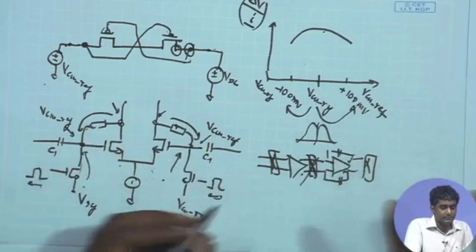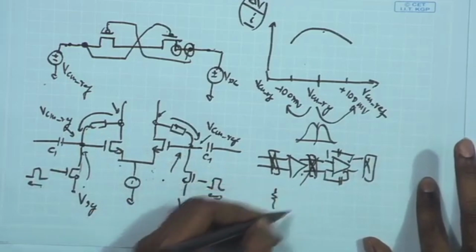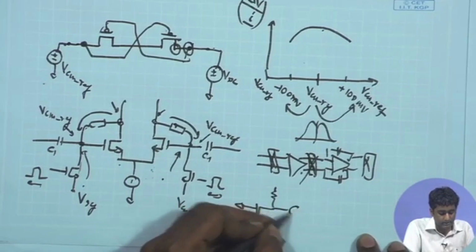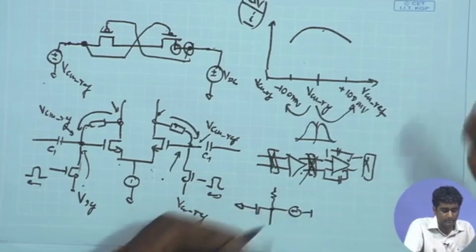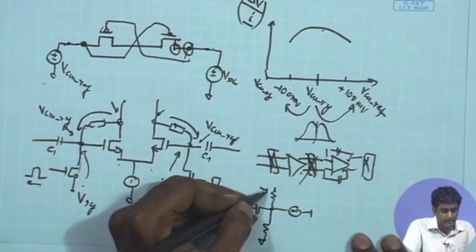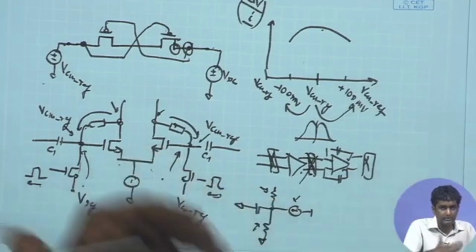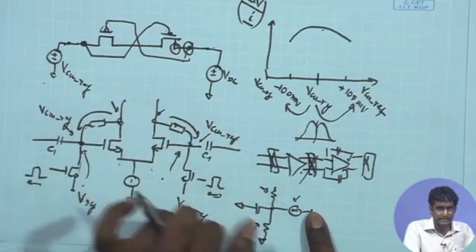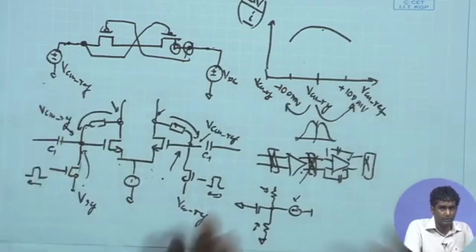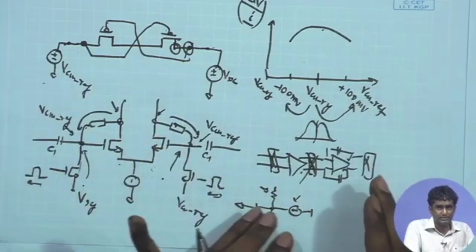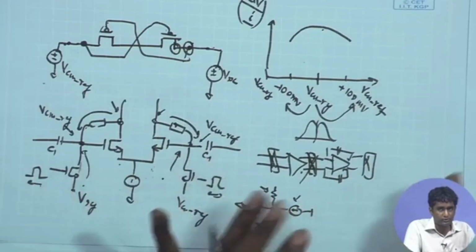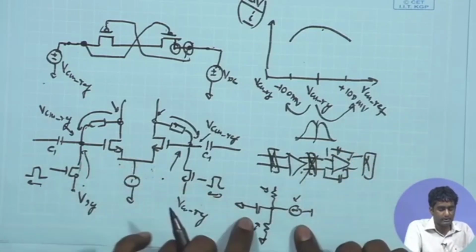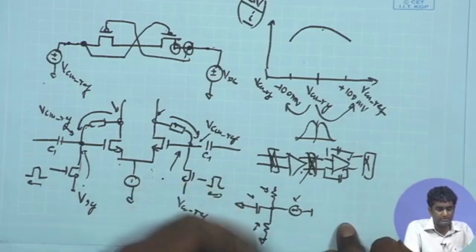Every time you have some circuit resulting from the DC conditions, you have some capacitors resulting from the MOSFETs, and you may have some dependent current sources with values dependent upon the MOSFET parameters. Even if you look at the large signal model, ultimately it will break down into equivalent resistors, capacitors, and dependent sources. So it will break the entire circuit down into these elements: resistors, capacitors, dependent sources, voltage-dependent current sources, current-dependent voltage sources, like that. And at every time step, depending upon the DC condition at different nodes, the values of these capacitors and resistors will change.